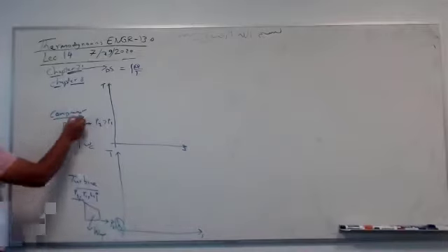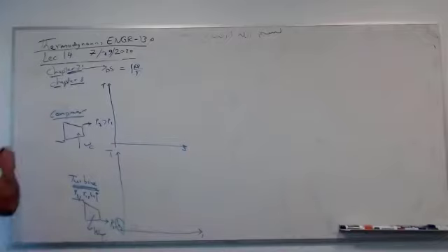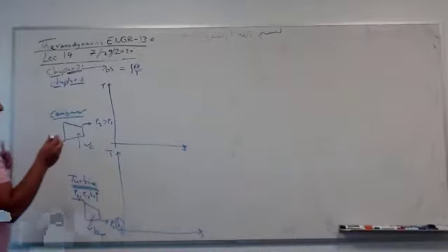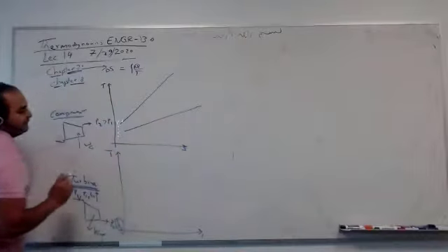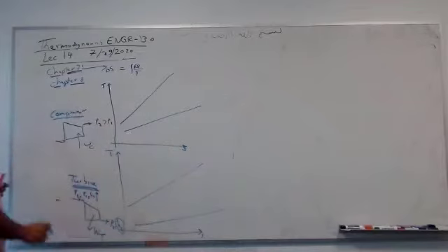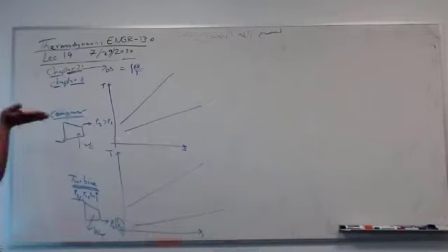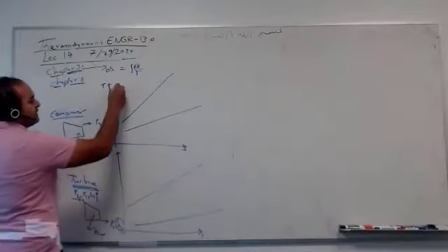So these components are parts of our systems, which will appear in the following chapters, chapter 9 and 10. So we need to understand what's going on here. Let's talk about the simple case now, ideal gas. The whole idea is that the pressure lines are diverging. This is always correct. If you plot the TS diagram, you have pressure lines, slope, flat, slope. We are plotting this for air, which is in the superheated region.